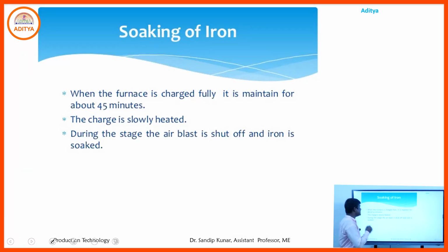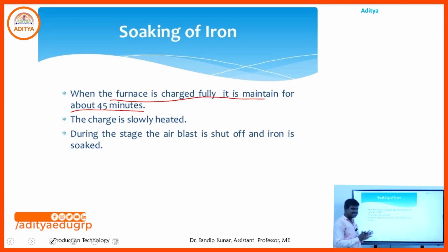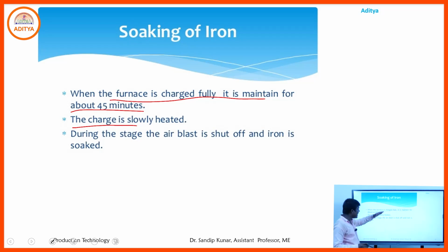Next, soaking of iron. In this stage the furnace is charged fully, meaning filled with the charge: metal, flux and coke. It is maintained for about 45 minutes. Then the charge is slowly heated.